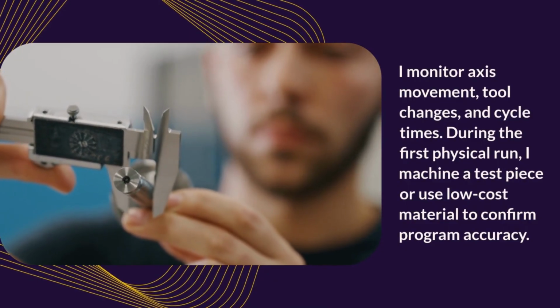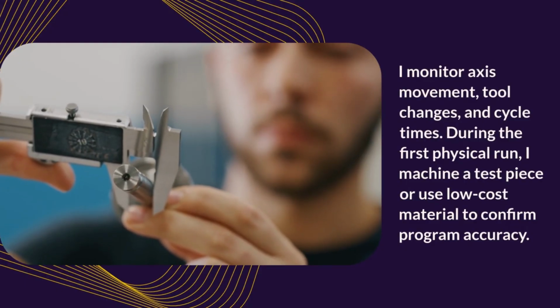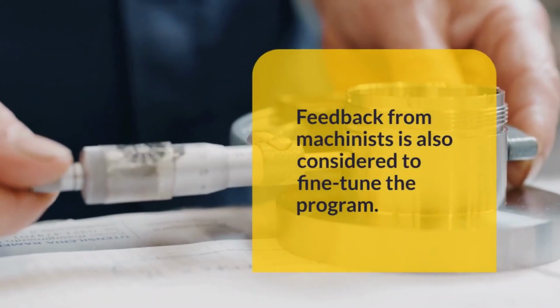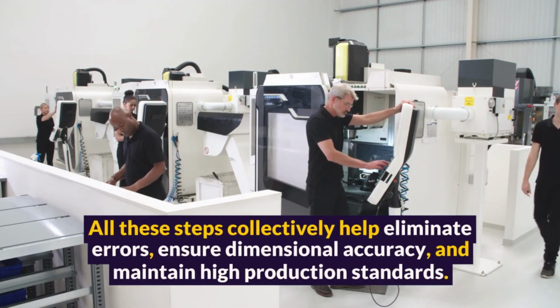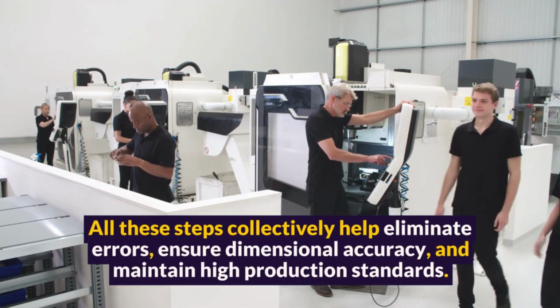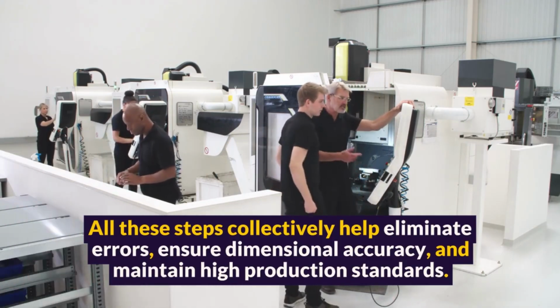During the first physical run, I machine a test piece or use low-cost material to confirm program accuracy. Feedback from machinists is also considered to fine-tune the program. All these steps collectively help eliminate errors, ensure dimensional accuracy, and maintain high production standards.